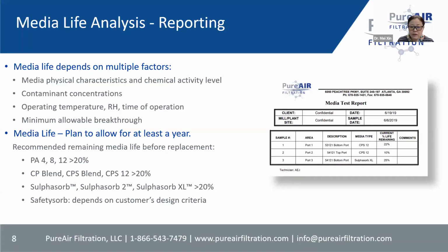Also, different customers have different minimal allowable breakthrough concentrations. So that will also determine when you need to replace your media. But generally, as a rule for the majority of products, if you see on the report that media life is close to 20% or below, it's time for you to order new media right away. For safety drop, which is an emergency gas media related to safety, different customers may have a little bit higher minimal remaining media life before replacement.